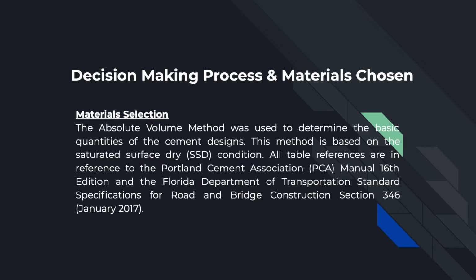Going into our decision-making process and the materials chosen, the absolute volume method was used to determine the basic quantities of the cement designs. This method is based on the saturated surface dry condition, SSD. All table references are in reference to the Portland Cement Association Manual 16th edition and the Florida Department of Transportation Standard Specifications for Road and Bridge Construction, Section 346.